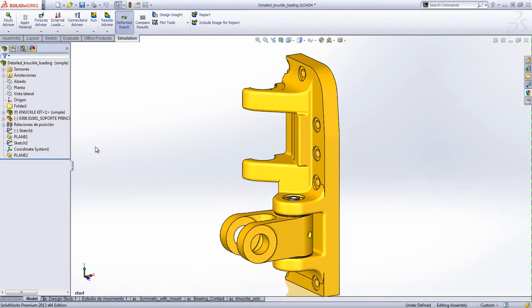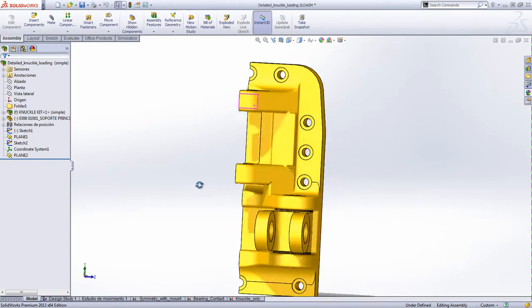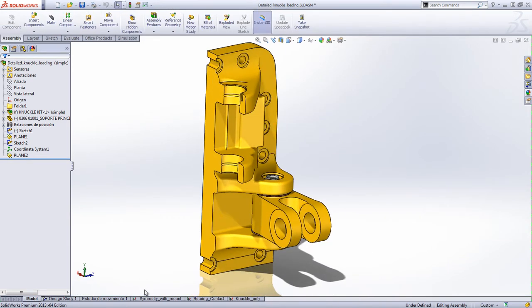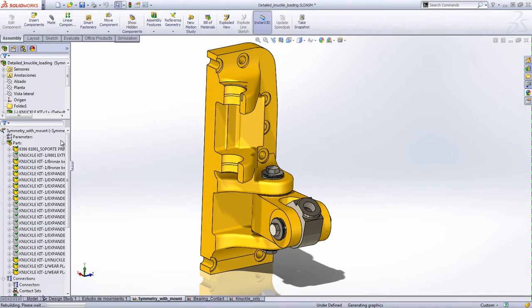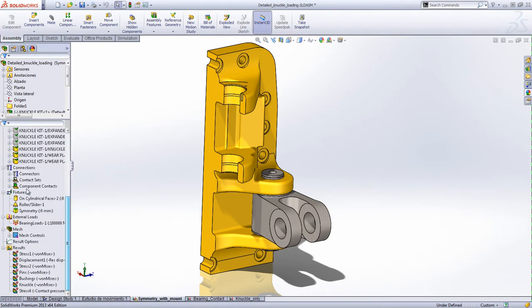When it is time to gain a better understanding of load paths and local stresses, SolidWorks simulation provides detailed results and can simulate complex interactions. For the case of the knuckle joints supporting the main actuators, there is complex pin bending loads that need to be accounted for to accurately represent the part connections. Taking the case for a symmetric load condition, we can model just half of the mounting plate and then focus on parts of the geometry we wish to study.